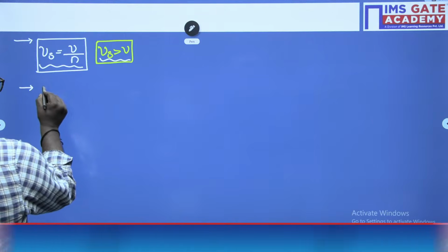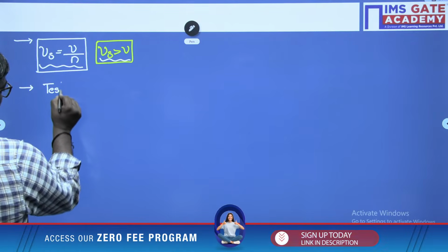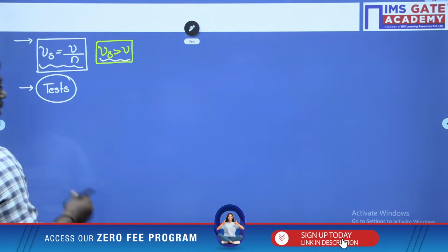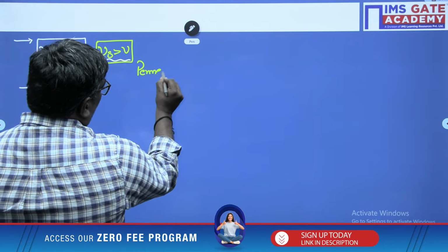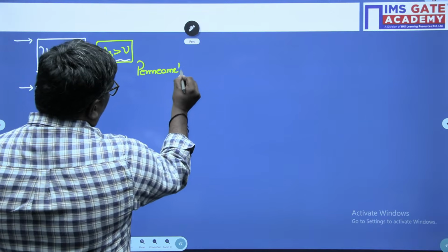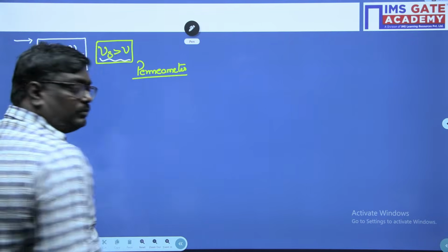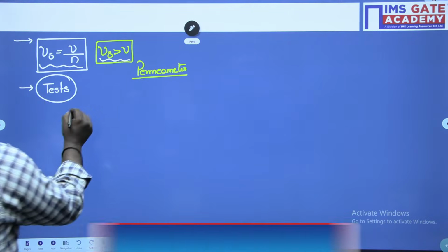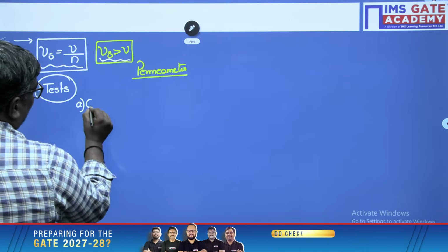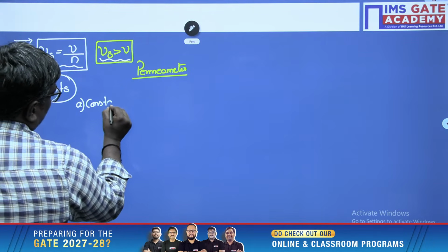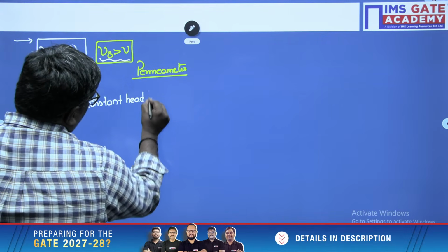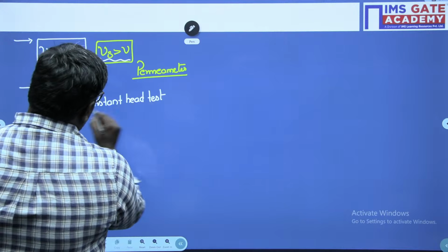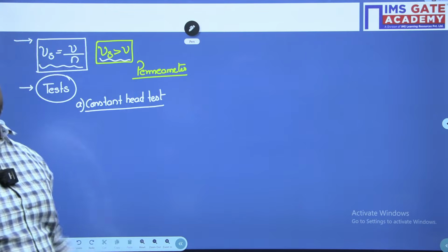Okay. Now see, sir, what are the tests to determine permeability? Now, my dear students, the instrument used for determining permeability is the permeameter. But we have different tests. In this, the first one we have is the constant head test. In the name itself, it is constant.